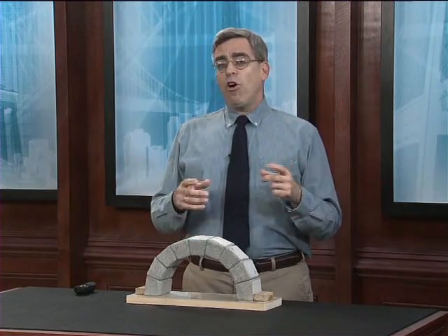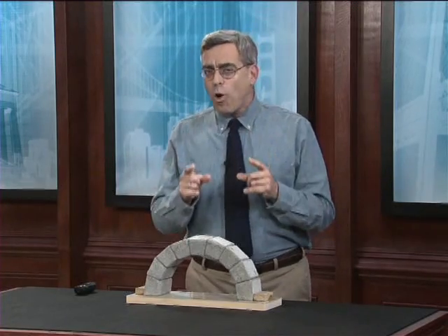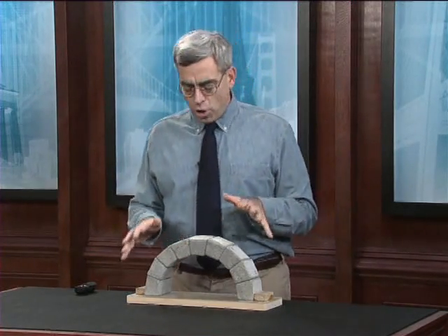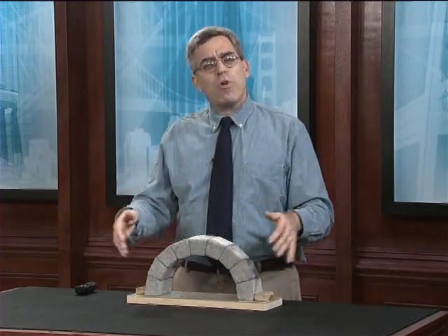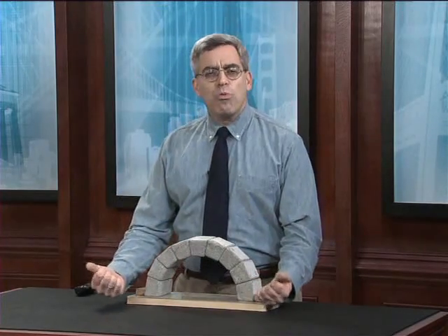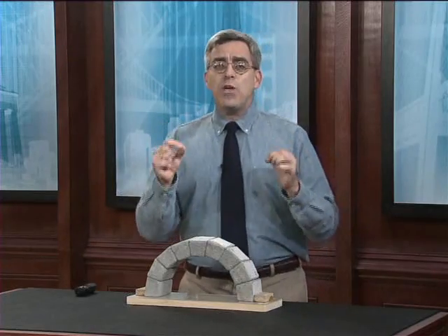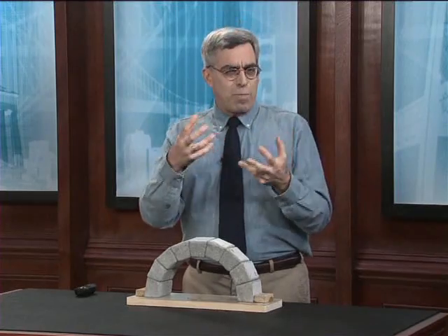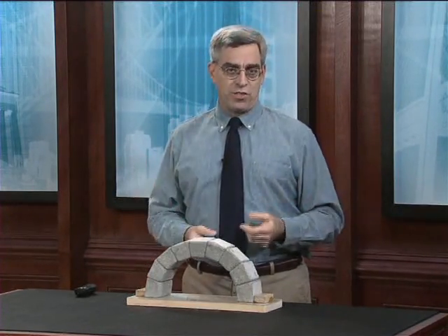But an arch can only carry load if it's adequately supported. The critical requirement for the stability of an arch is its lateral restraint. As you remember from Lecture 8, under load, an arch has a natural tendency to flatten and to spread out laterally. That lateral spreading of the bases of the arch is called thrust, and thrust must be resisted. It has to be restrained by some sort of physical device, by some physical mechanism that supports and prevents that lateral movement of the bases of the arch.